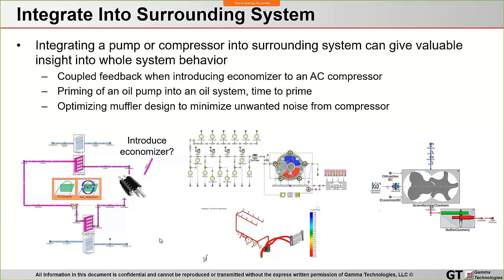And then another example would be looking at priming of an oil pump in an oil system. A common thing to look at on the hydraulic side is this concept of time to prime. Here you can see an example animation showing a system that's initially filled with air, and then it looks at transient filling or priming of that oil system. The detailed hydraulic pump can be included to give an accurate prediction of the time to prime.